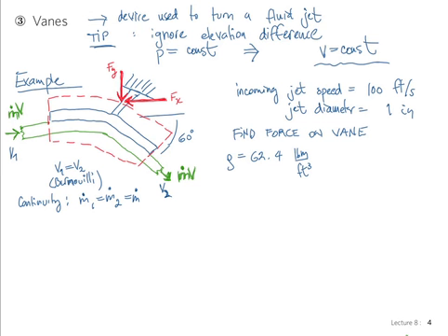Yes? I said a little while ago that the way you choose the control volume in the middle section doesn't matter because the velocity is 0. What velocity is 0? The velocity of the fluid. Because the velocity of the fluid is 0 across this surface, I don't care about the shape it has, because I'm not going to have to write a contribution to that integral across the control surface for the fluxes of momentum.